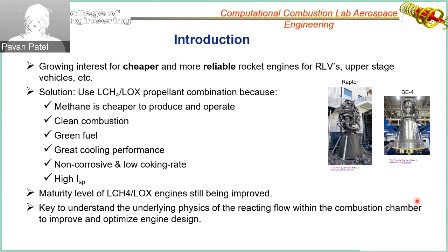One way we can reduce the propellant is if we change our propellants to something like methane, and methane has many advantages over hydrogen and RP1. They're listed here, but although the ISP of hydrogen is much higher, the overall benefits of using methane are significantly higher.